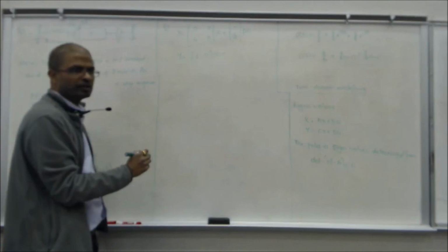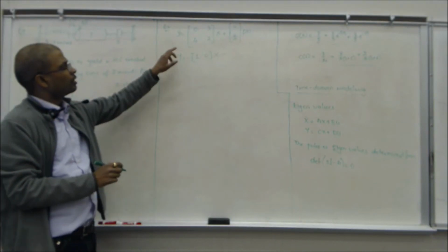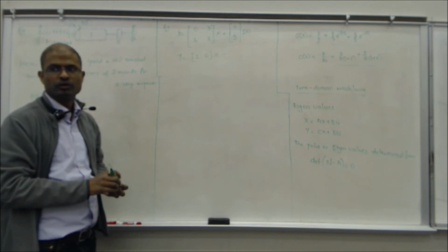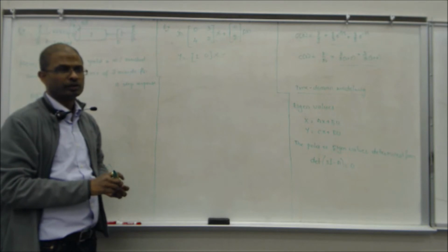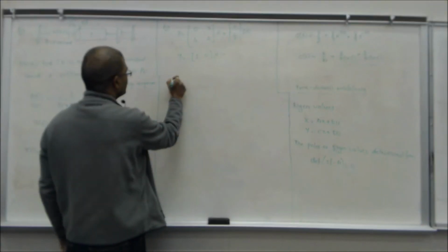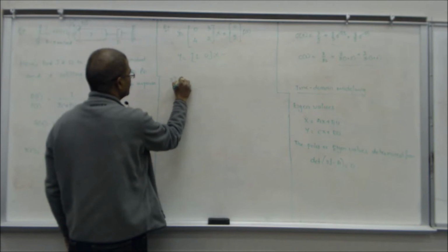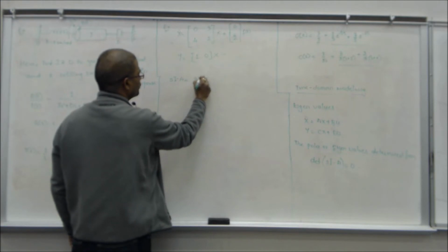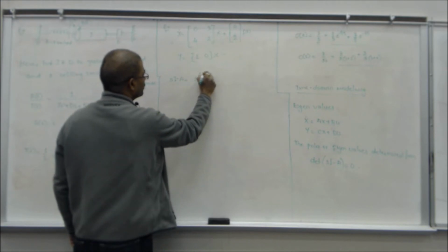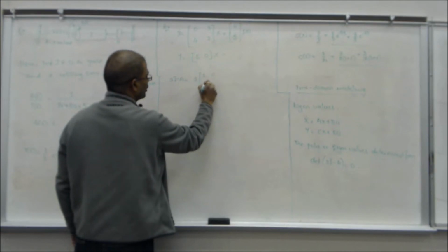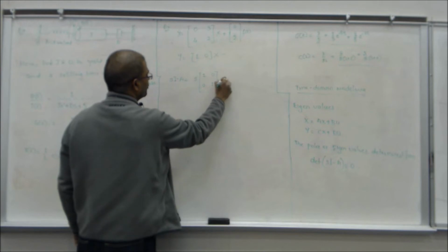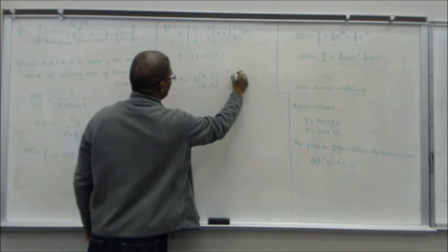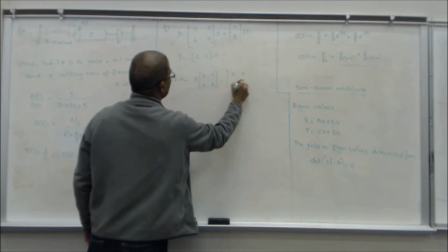So what is sI minus A? What is the order of A here? It's a 2 by 2 matrix, right? The order is 2 by 2. So you build sI minus A like this. Have the s variable multiplied element-wise by the identity matrix, minus, and I think we have done this in the lab, right? 0, 3, 4, 2.